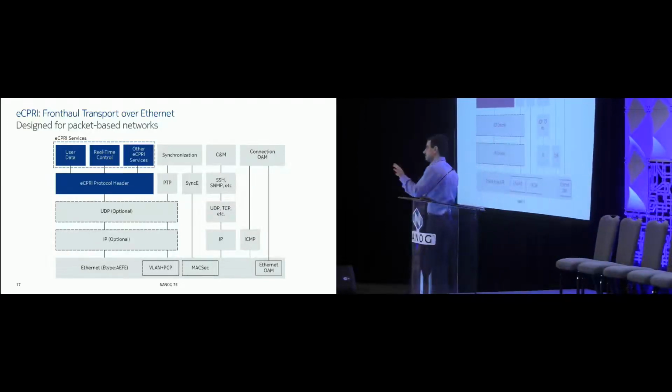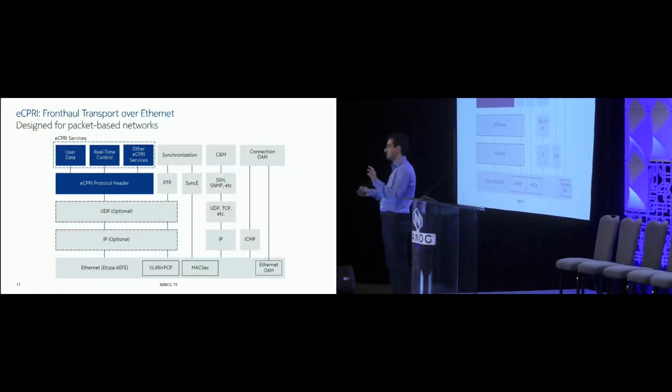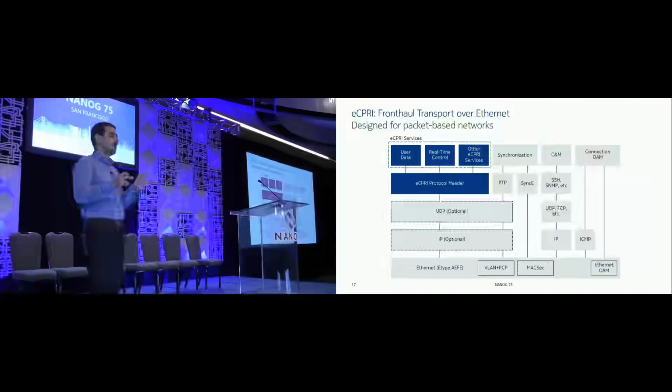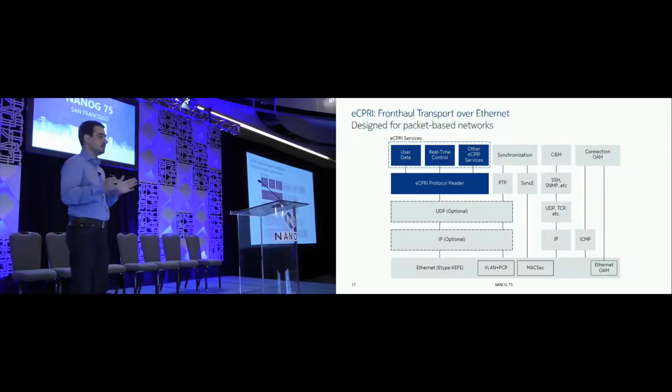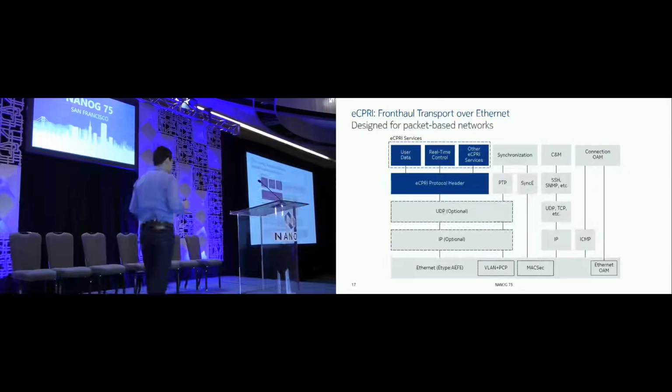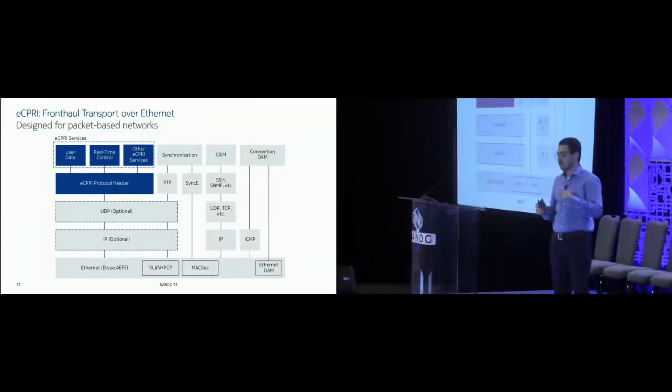Instead of using a single chunk of spectrum or channel for uplink and another channel for downlink, you use a single chunk of spectrum and you split logically what you want to use for downlink and uplink. Because it's a time division duplex characteristic and not frequency division duplex, you now need time and phase synchronization for 5G. That is mandatory.